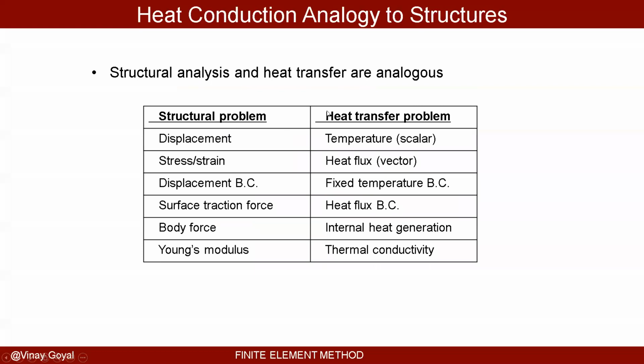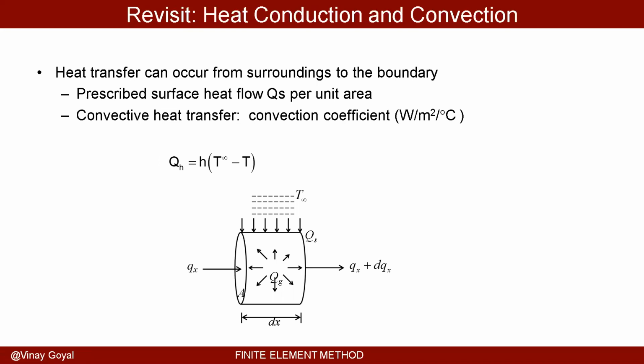Instead of deflections, you're calculating temperatures. Instead of stress and strain, you're calculating heat flux. Instead of fixing deflections, you're fixing temperature. Instead of applying tractions and loads, you're applying heat fluxes. Instead of body forces, you're applying heat generation. And instead of Young's modulus, you apply thermal conductivity. There's some analogy in these ideas, and they're worth discussing.